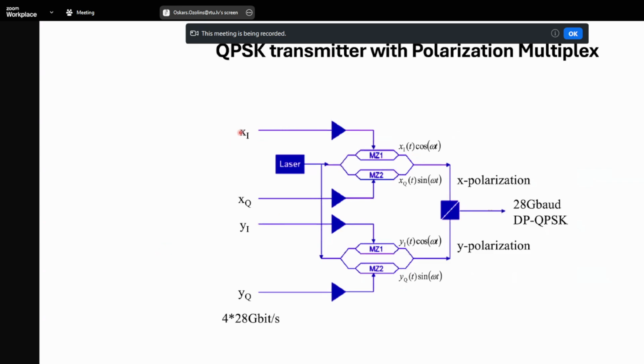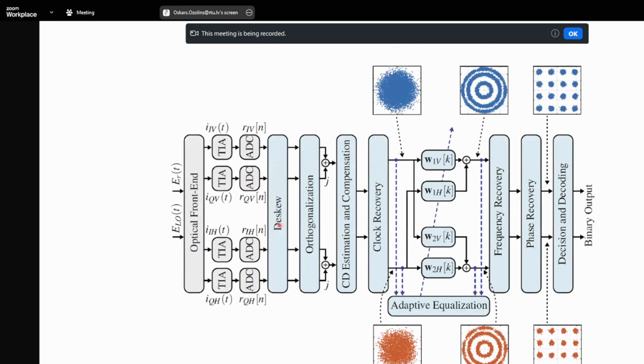So here we see also four channels coming here. The electrical signal in each path coming to the modulator can have a different propagation time, which means that you might have a skew in your signal, and there are different ways how to optimize that, and there are ways how to compensate that. We are not going to cover all the possible sources and how to tackle those sources. There are plenty of research papers available that cover each of these